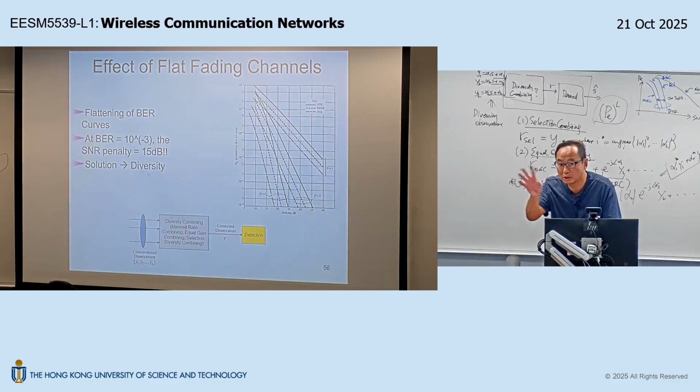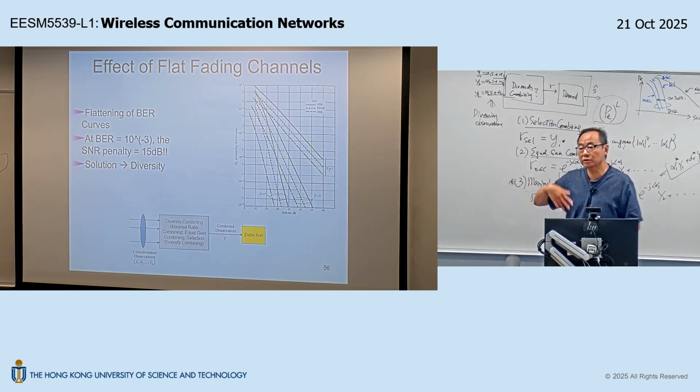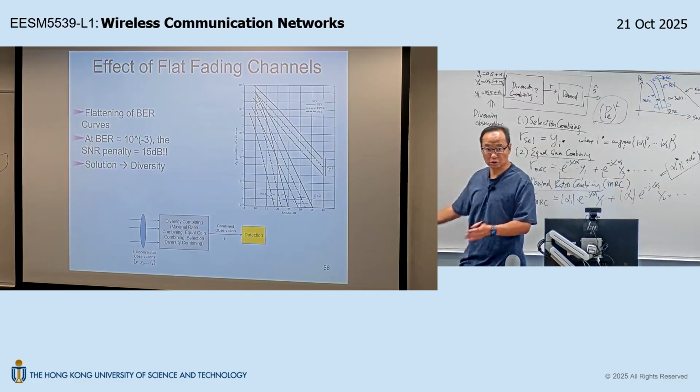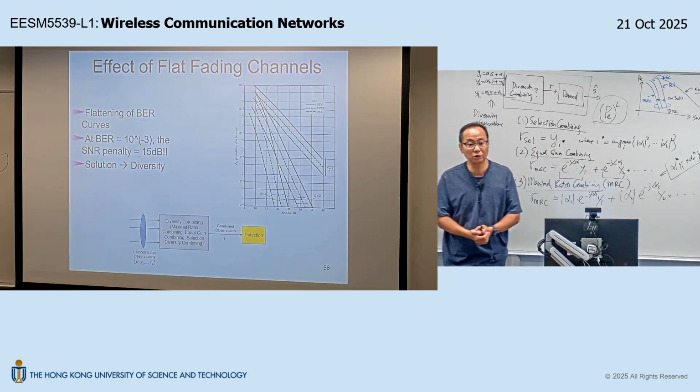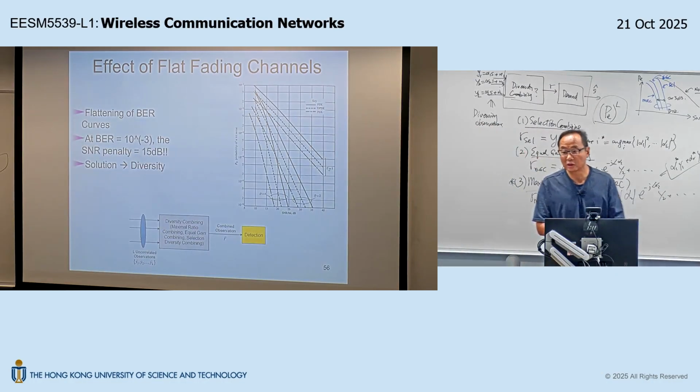Let's say you go through link budget analysis. You figure out, okay, diversity order of 2 would be sufficient, right? With 10 to the power minus 4, if you have diversity order of 2, the signal-to-noise ratio reduces to 25 dB. So let's say with 25 dB signal-to-noise ratio, you got 15 extra dB in your path loss. And that 15 extra dB translates to, let's say, 1 kilometer coverage, which will be sufficient for your application. Okay? Let's say it's something like this.